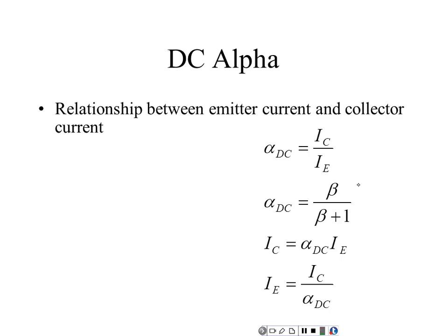We have 2 ways we hook up a transistor, by the way. We got 3 leads, and we can make one of the leads common to the input signal. So we have what we call a common emitter. What would the other one be? Common collector, common base.